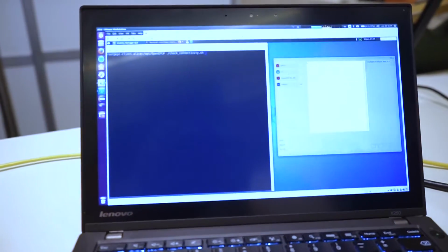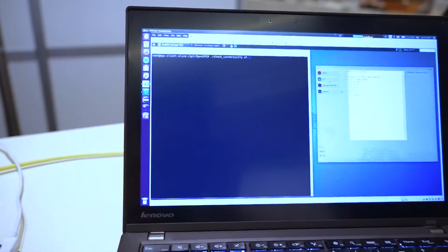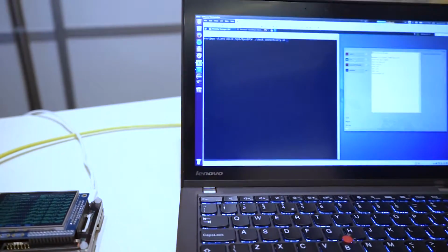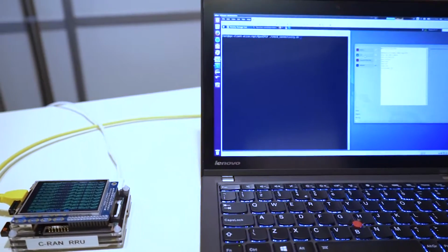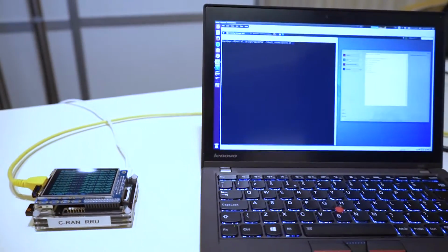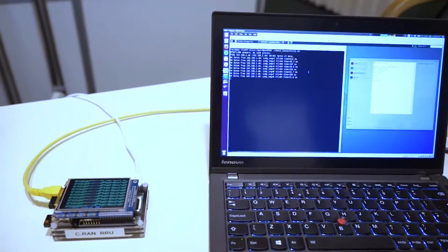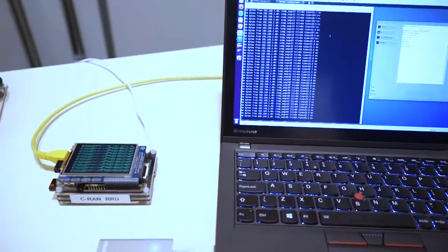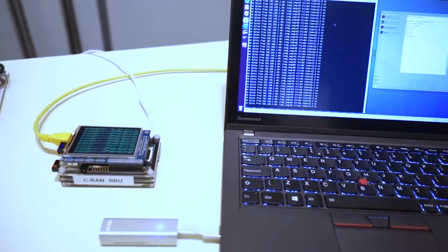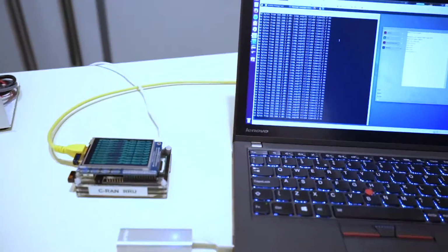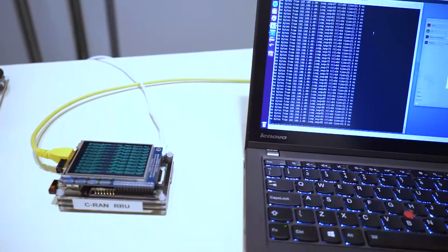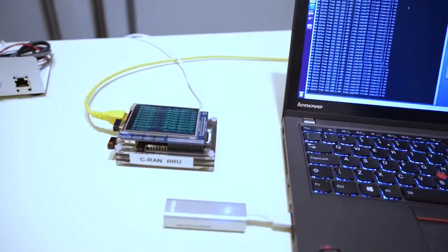All of this enables us to establish a default bearer to have a connection with the core network and the PDN network connected to it. We can also check the connectivity, and as I mentioned before, the front haul link is done over a wireless optical link, which means whenever a connection is interrupted, the connectivity is dropped. And as soon as it's resumed, the connectivity is back up.